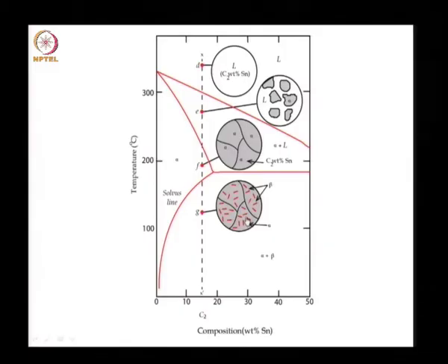So, you see here that as we go through the different regions, the microstructure changes. We saw previously in the case of lead rich alloy with very little tin, we had a microstructure such as this, where we had only the alpha phase. But now with a higher tin content, as we go into the alpha plus beta region, we have the microstructure changing from this to this. Here we had only the alpha phase, and now we have a beta phase inside the alpha crystals forming.